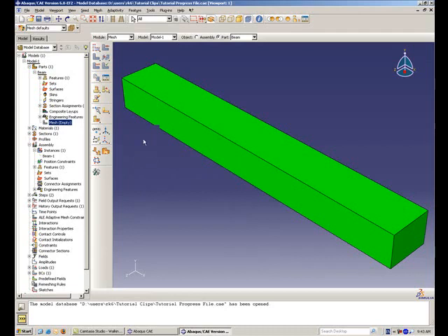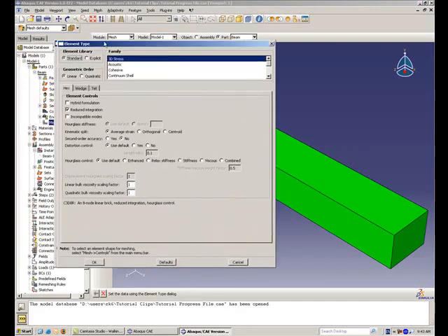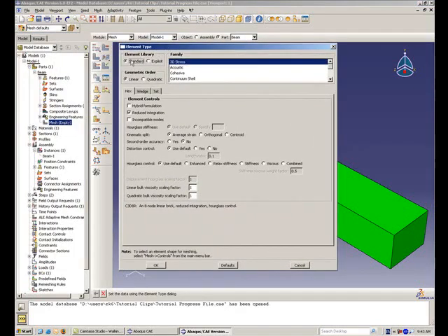Using the main menu bar again, select Mesh and then Element Type. Accept the standard linear and 3D stress defaults, but click Incompatible Modes in the Hex tab. Examine the Wedge and Tet tabs for future reference.